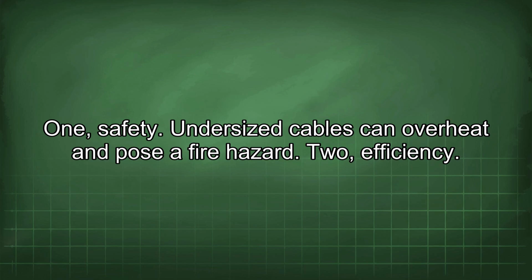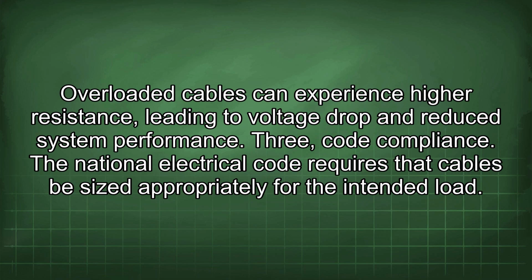1. Safety. Undersized cables can overheat and pose a fire hazard. 2. Efficiency. Overloaded cables can experience higher resistance, leading to voltage drop and reduced system performance. 3. Code compliance. The National Electrical Code requires that cables be sized appropriately for the intended load.